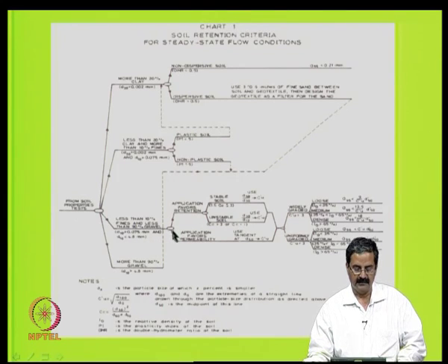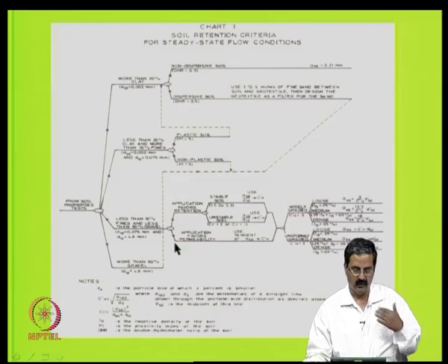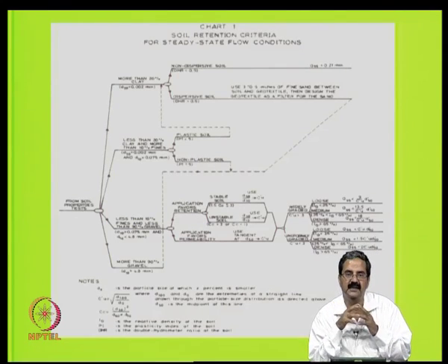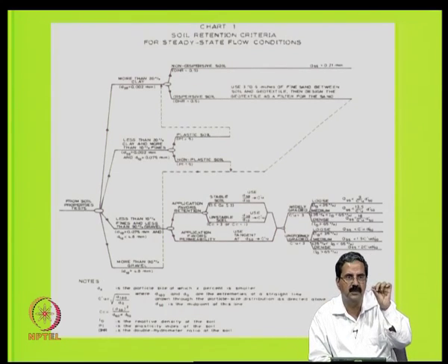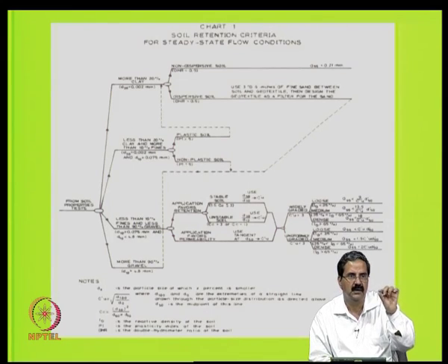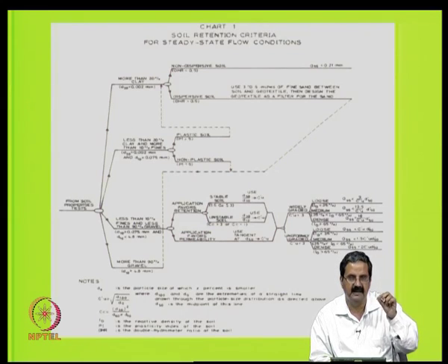We should also understand that there is a difference in terms of application. Do you want water to flow, so that the application should favor permeability, or do you want soil retention? You have to choose. There are two things here: the flow of water and soil retention. From the point of view of soil retention you need small pores, but in terms of the permeability criteria you want big pores. You understand, they are contradictory requirements. So it is based on the grain size distribution only that you want to get everything.